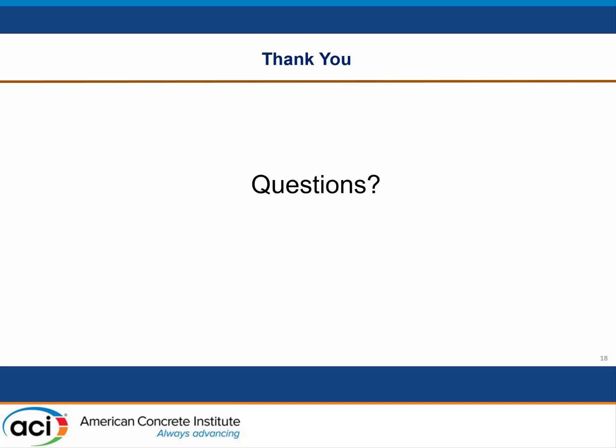Yeah. And I'm going to answer this as my personal opinion. If you ask the other presenters in this session, you'll probably get slightly different answers. I think the acceptance criteria are a little bit conservative. I think it's relatively simple to get a simply supported member to pass the load test, and it's even easier to get something with continuity. It probably is a little bit harder now with the cyclic load testing method, but all of these load tests, we always load test structures because there's a problem. It's very rare that we go out and load test a perfectly good structure.